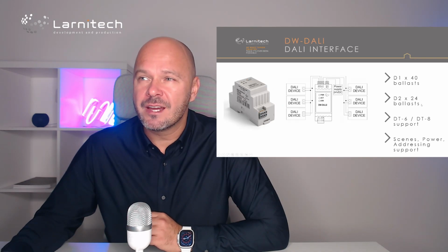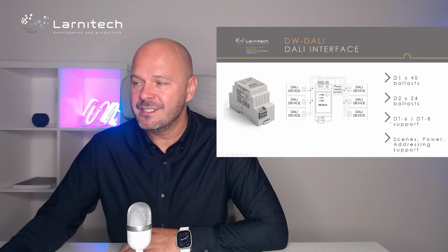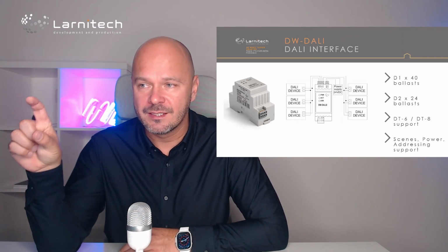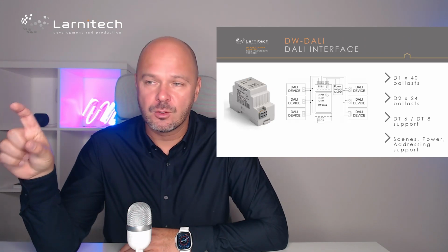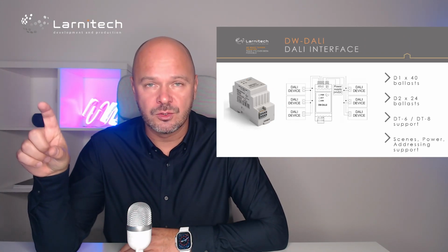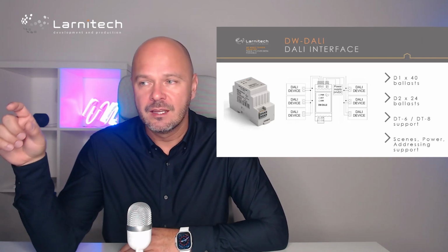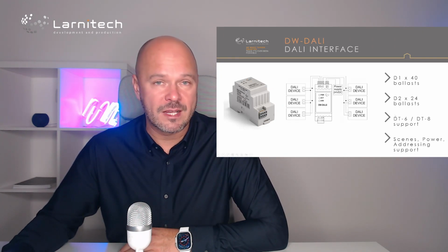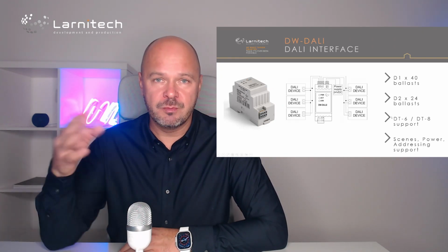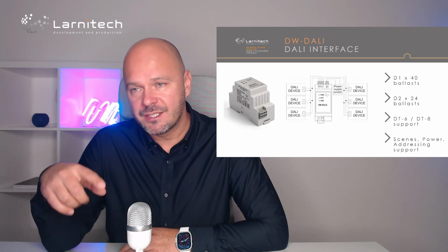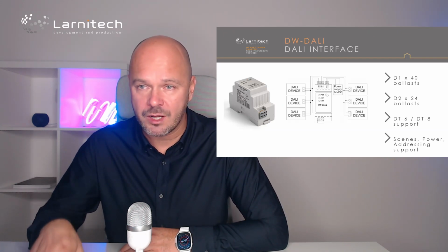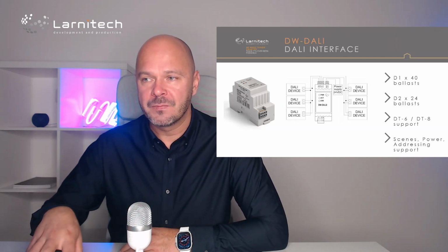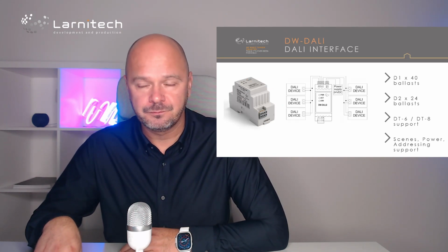There are also types of DALI addresses. The DT6 type is when we control only one DALI address and device. Like normal white, normal red or normal green, we just dim each of them directly with a DT6 address. And if you want RGB or RGBW, you will need a separate script. We have the script for RGB, for example, and then 3 normal dimmers become color dimmers.